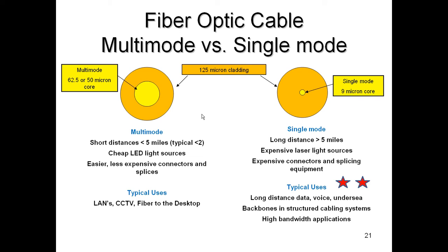But you know what? The cable that they buried probably has 6, 12, or 24 fibers in it. Why did they pull the extra fibers? Well, first of all, it is made of glass. There is the potential of breakage when you install it. Even though we're going to talk about how to install fiber so that you don't break it, if I need two fibers to work between these two buildings and I pull a 6-count fiber, I can break one and I still got 5 left, so I'm still good to go, right? That's one reason that they pulled the extra fibers.